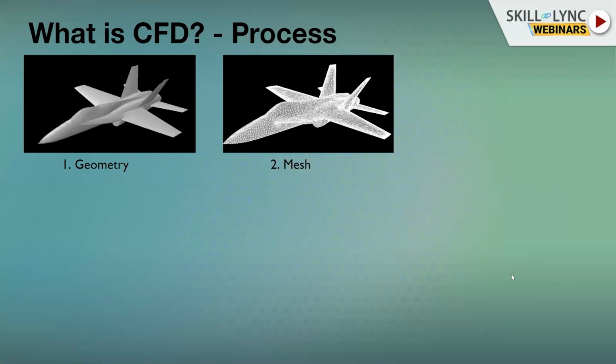The purpose of mesh generation is that the equations we saw in the previous slide are continuous. We are trying to solve a differential equation and an integral equation. They are continuous in nature. And those equations are valid within these small control volumes, or the mesh. From one mesh to another mesh, there could be a discontinuity, or it could be different. This is called the weak solution. That is the primary purpose of generating the mesh.